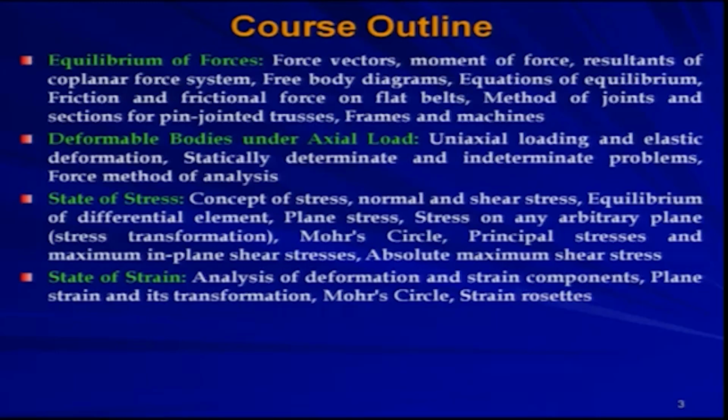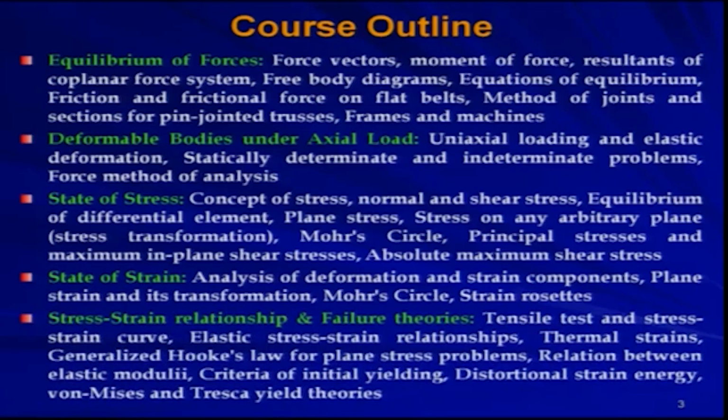It includes analysis of deformation and strain components, plane strain and its transformation, Mohr circle and strain rosettes. Next is stress strain relationship and failure theories. It includes tensile test and stress strain curve, elastic stress strain relationships, thermal strains, generalized Hooke's law for plane stress problem, relation between elastic moduli, criteria of initial yielding, distortional strain energy, von Mises and Tresca yield theories.